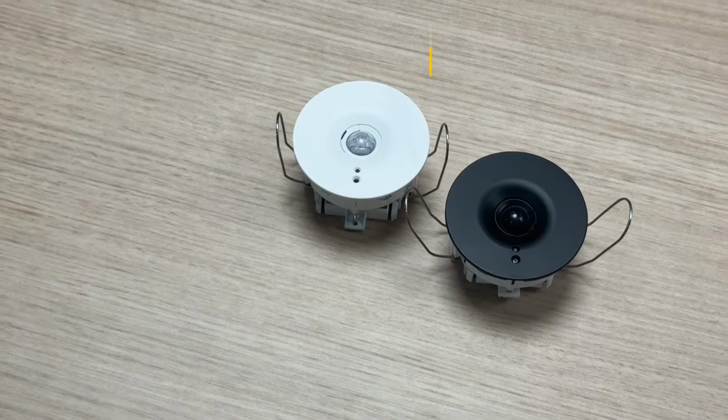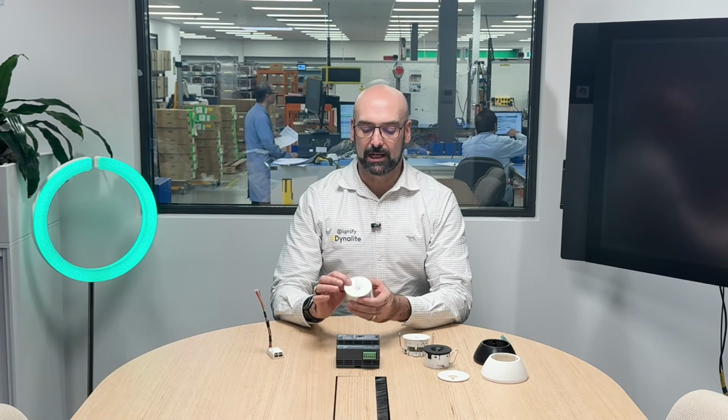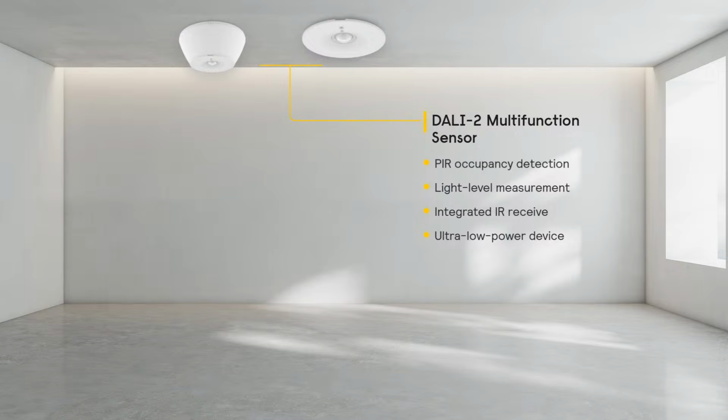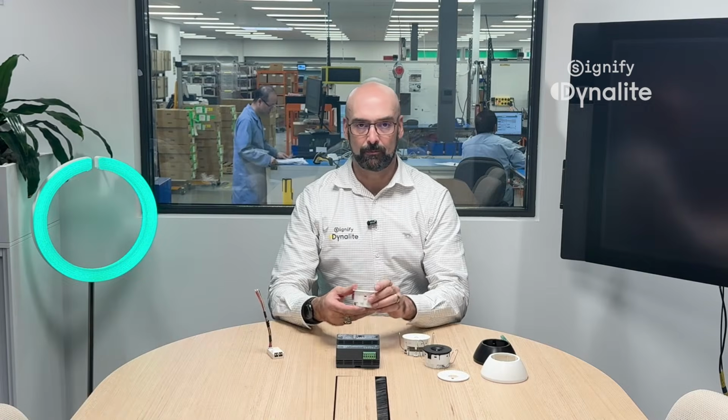So to start with, we have updated our sensor. This is phasing out our previous generation sensor. It is the same size, so completely retrofittable back to the original cutout. We're retaining a lot of the features, so we still have our PIR mask, being able to stop the anti-trigger detection for doorways. We have our light level receive and our IR receive, all on the same device. It still sits inside the same form factor, so very robust and very useful.